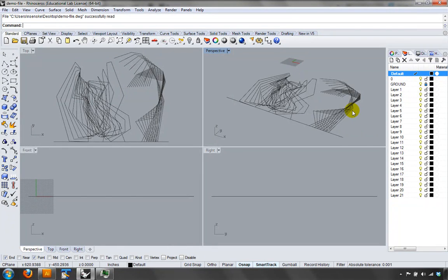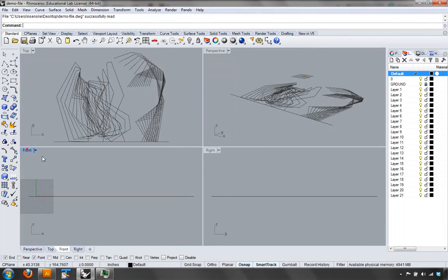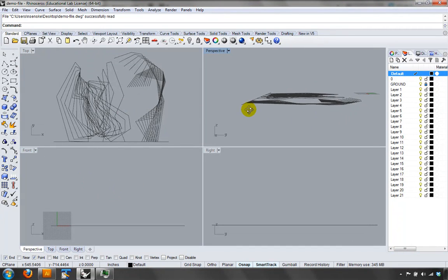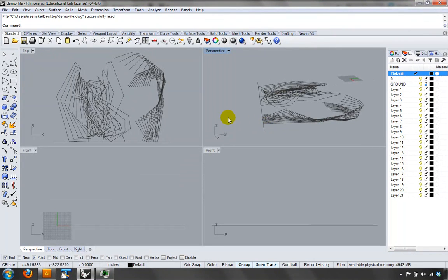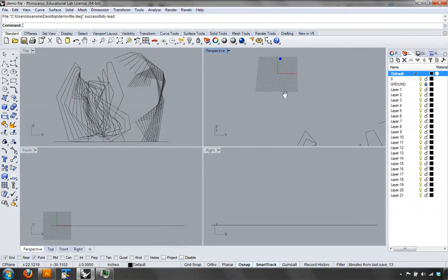Okay, so I have all my objects, but I have two problems. One, these are sections, and if we're looking at them in our elevation views, they are not oriented correctly. We ought to see this right in the front view, and it's not. It's actually laying flat, like we took a drawing in. So we need to rotate those in 3D space. And the last thing is that they're not to scale. I can just tell you that they're not. If you look at the grid, this is usually a 10-foot.